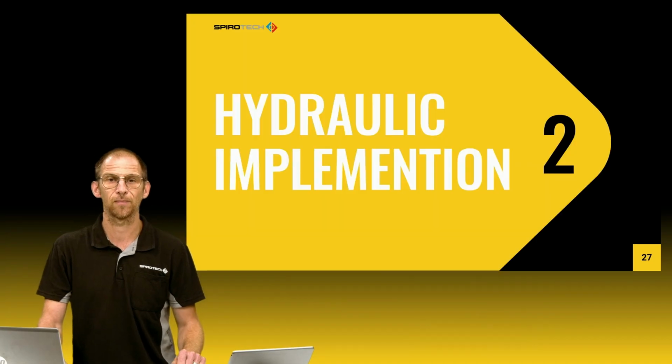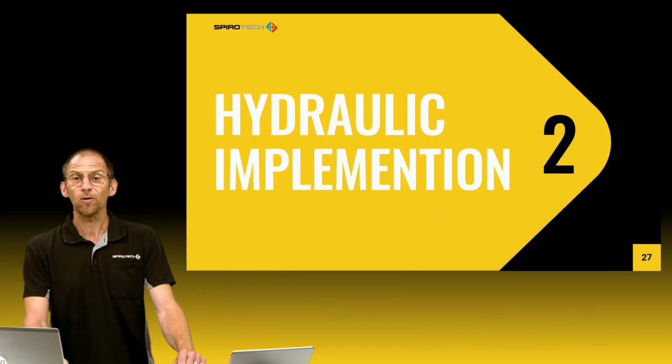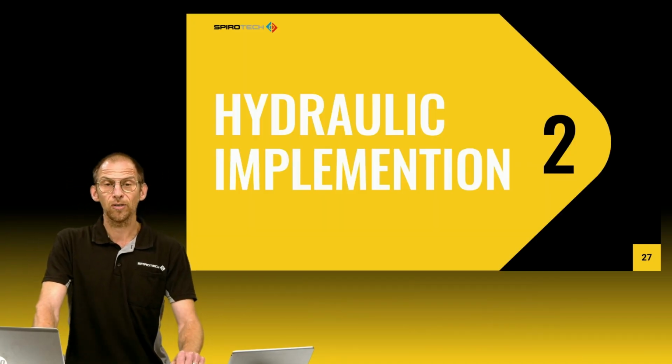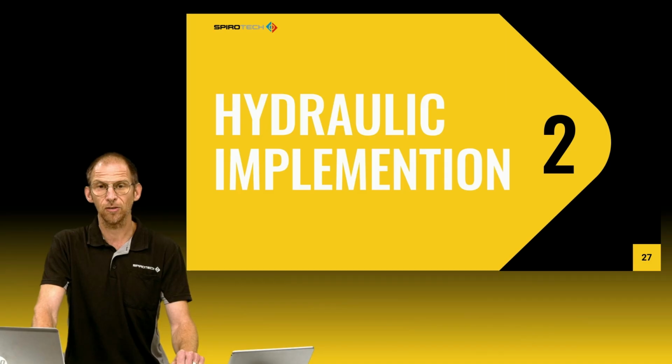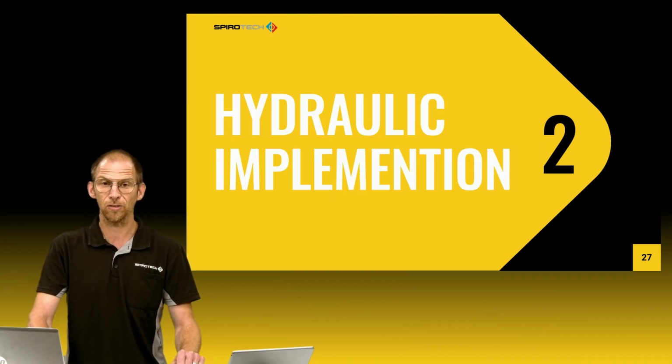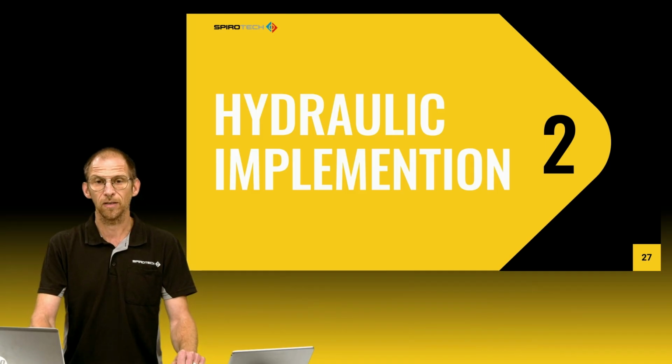All right. We'll now continue with this pressure profile and look at how the connection point of the pressure maintenance system affects the pressure throughout the installation. Changing the connection from the pump suction side to the discharge side or elsewhere changes where the profile is anchored and therefore which parts see higher or lower pressures under operation. In the next slides, we'll compare these setups and highlight what shifts you should expect.